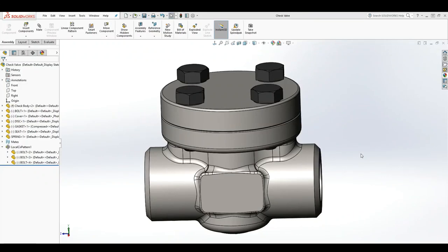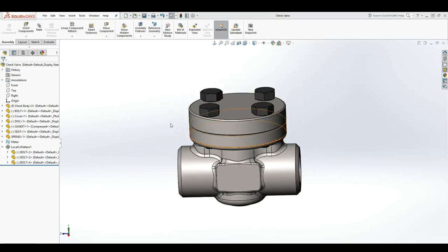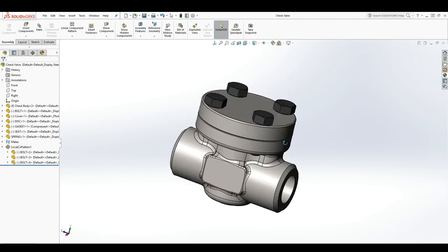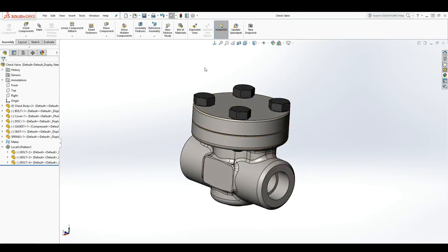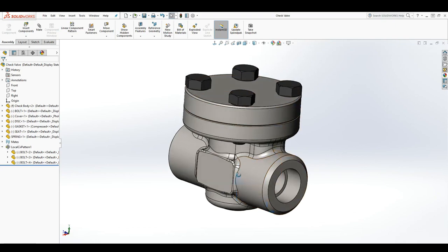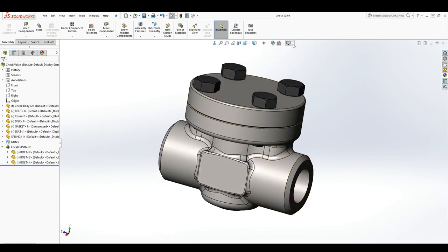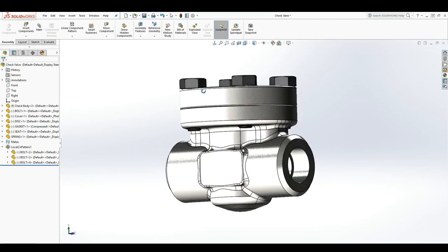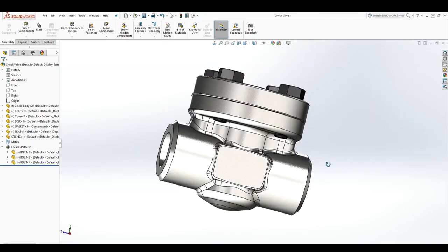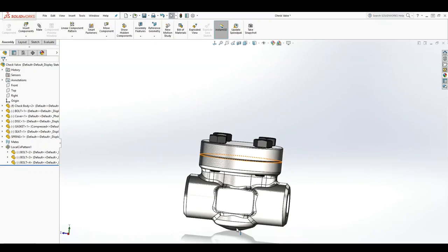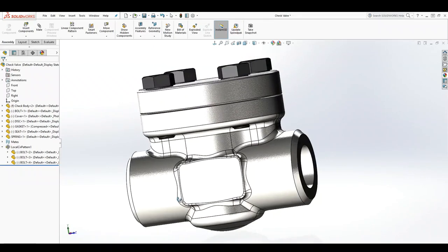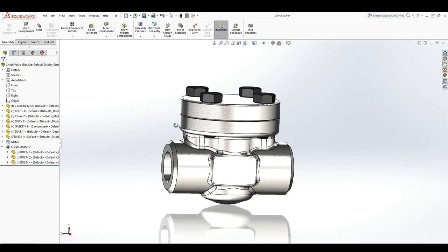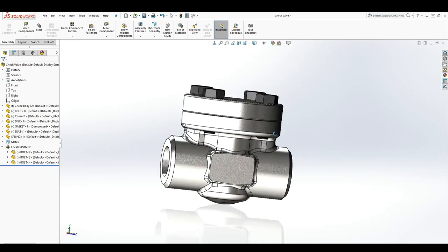So in this lesson we are going to be learning how to change our scene in our valve assembly. So we have our assembly here, and a couple of things we can do to actually get this model looking good is right under this view setting, we can turn on real view graphics. So now when you have a good graphics card in your computer, you actually see a more fine definition of that appearance. Now as you can see, we can see that carbon material very well.